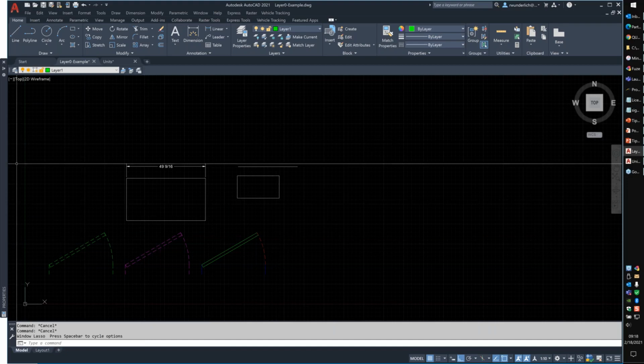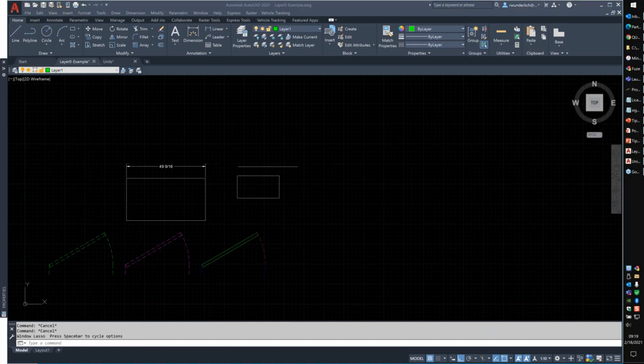And how would you handle some of this with dynamic blocks? Well, that depends, Brad. You can certainly set dynamic blocks with their own layer information, display states, and things like that. Really, you just have to be cognizant of the fact that anytime you add an override or you set layers, if you do not insert them on the correct layer, you're going to get some strange behaviors.